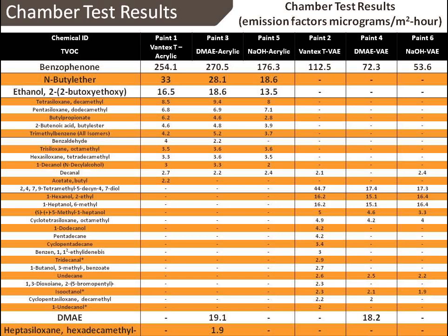Now I work with Tomeko, the amines company, so most of our work is relevant to amines, and amines are used as neutralizing agents in paints and coatings. But what we did here was to take 3 zero VOC paints, a formula based on an acrylic and a formula based on VAE, and we used 2 what were regarded as zero VOC neutralizing agents, and then we used 1 material which we knew was a VOC, dimethylaminoethanol, a low boiling certain VOC, and we did pick up some micrograms per meter squared per hour of the volatile material.